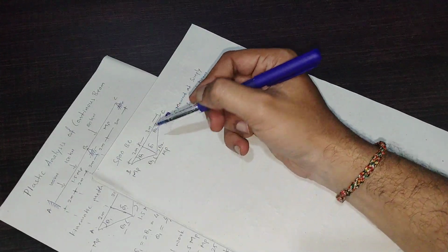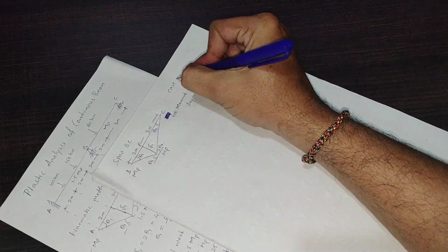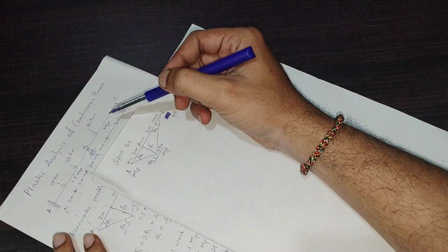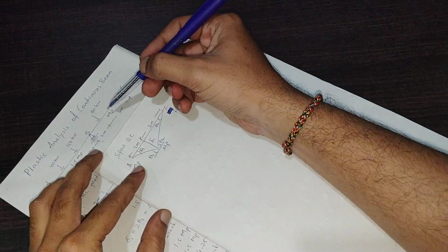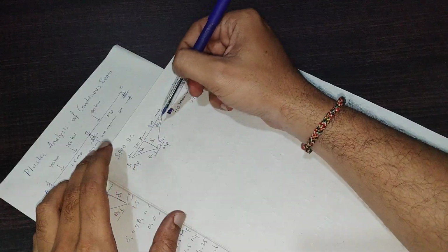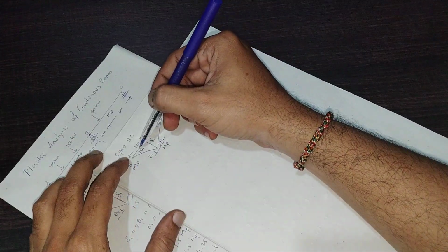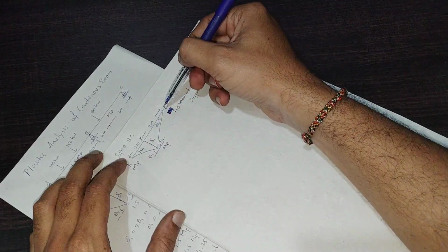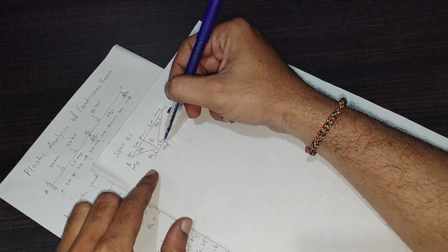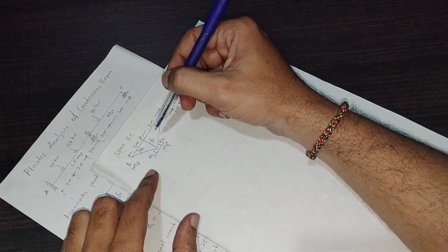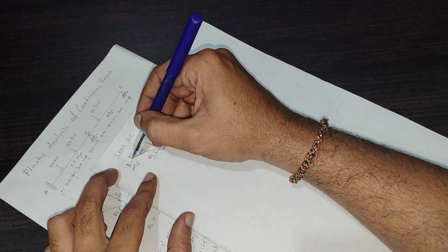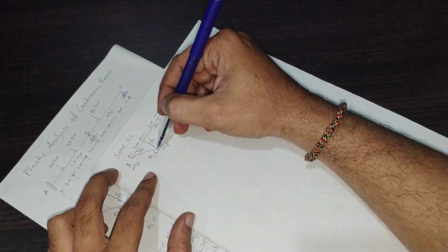Now mechanism 3 or case 3 for span BC. For the span BC, the case 3 is to be done under the load of 80 kilonewton. So under this 80 kilonewton load acting on span BC, the rotations are expected to be theta 1 on the support B, theta 2 on the support C, and the opposite angles theta 1 and theta 2 at the point under the load, and plastic moment is expected at point B or support B, which is continuous and under the concentrated load.